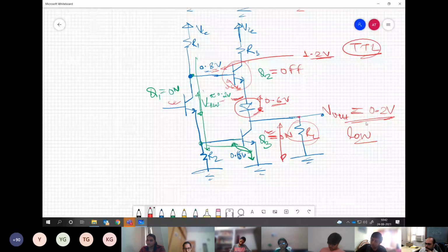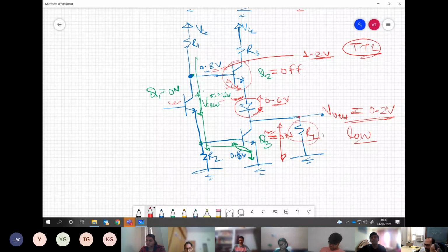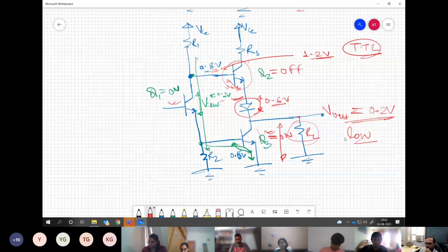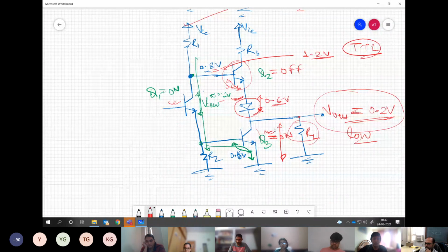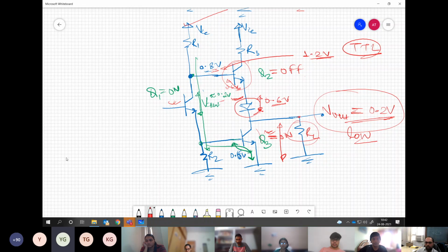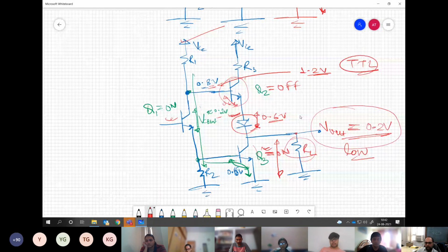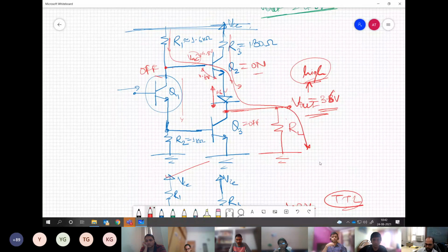technology, transistor logic. The outputs are not driven by what load we are putting. It is driven by what circuit configuration we have internally. So the drops across the transistor, diode and all these things are dictating what output voltage will appear over here for the given VCC. Understanding my point? Yes or no? Yes, sir.